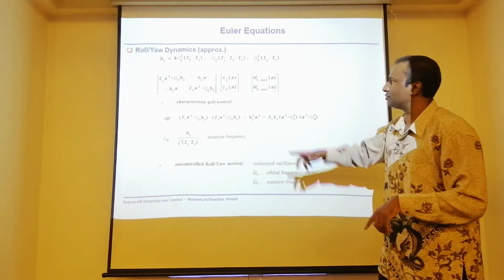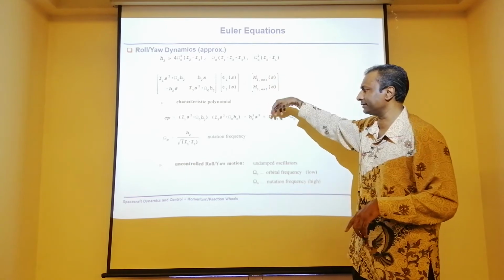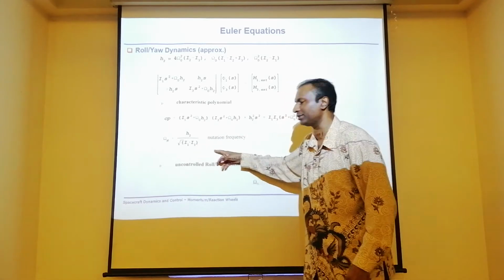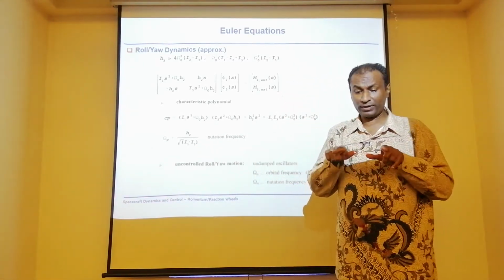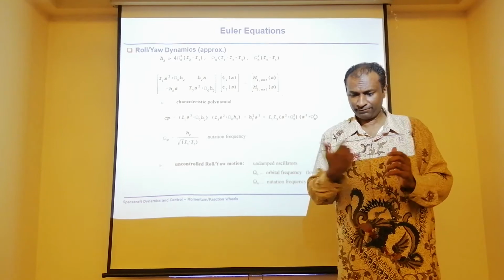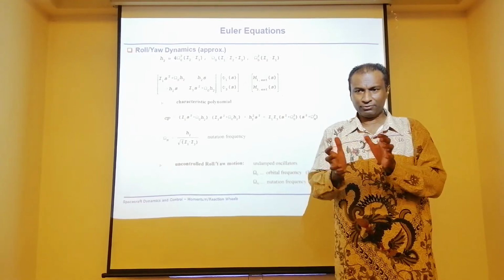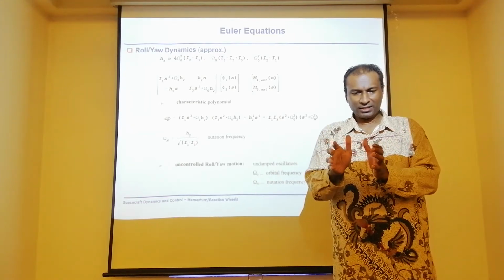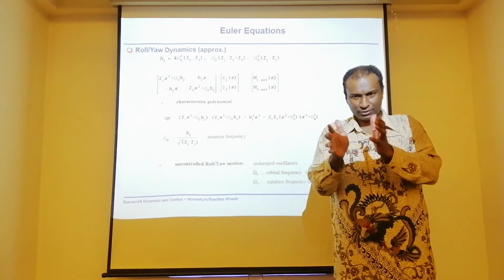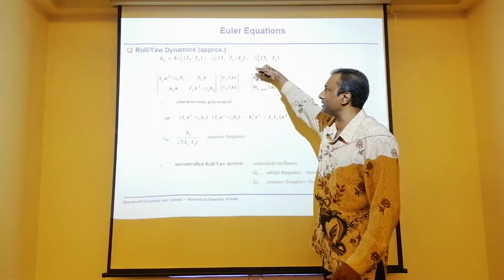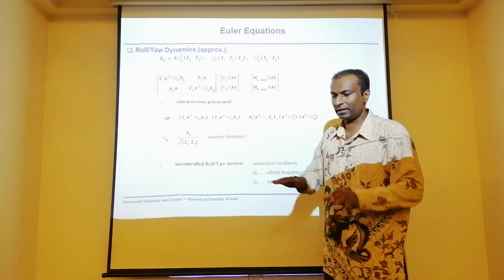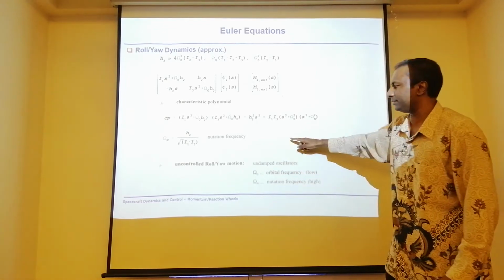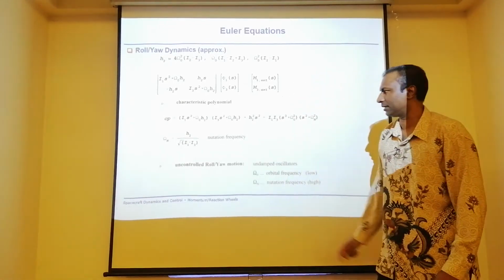Gyroscopic stiffness. When we do an analysis, it seems that it produces slightly a nutation. There is some nutation frequency. Why is there nutation frequency? Because when you produce a stiffness, this is stiff. If you throw a top spinning at high speed, you can see it is not just stiff like that. It may wobble like this. So that means the two other axes, roll and yaw, might also have a bit of nutation. Okay? So the nutation frequency can be calculated.